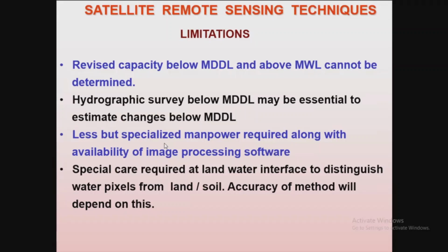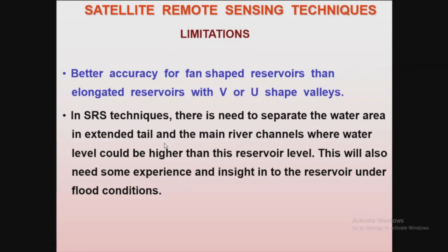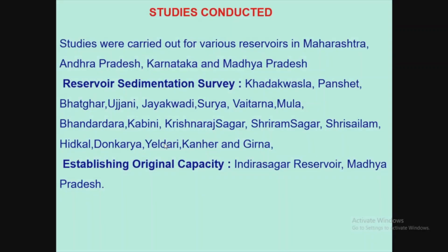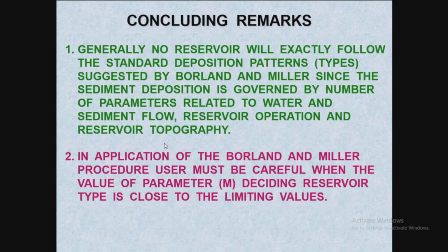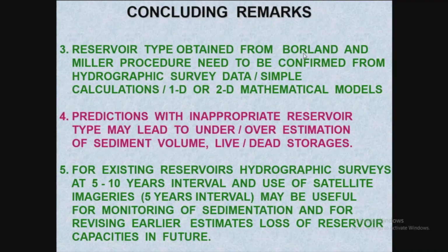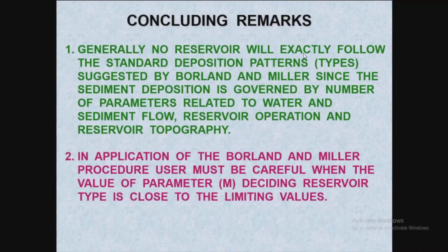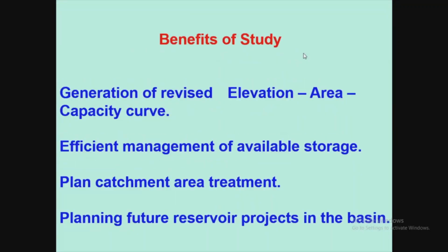Last but not the least, a hydrographic survey below MDDL may be essential to estimate the changes below MDDL, because we cannot do it by satellite imagery, so we have to do a hydrographic survey. So we have to use an integrated method sometimes, and take special care, because the students doing it should be highly skilled and should know the software, otherwise there will be huge mistakes. These are some of the important aspects. I'm not going into that detail. It's less tedious and requires less manpower. Even your professors can guide you at your place, and you can choose a nearby reservoir and collect the data, so it will be beneficial for you.